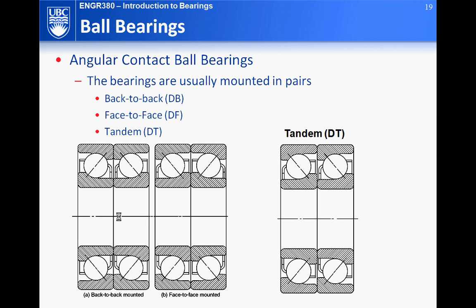And this one here is not as rigid as the other one, but it does provide more flexibility in terms of alignment. So A is mostly used more than B. That's the angular ball bearing if you use it in a pair. Tandem is essentially pairing them not in opposite directions, just two arranged in the same direction. It gives you more capacity in taking care of the thrust load, the tandem type of arrangement.